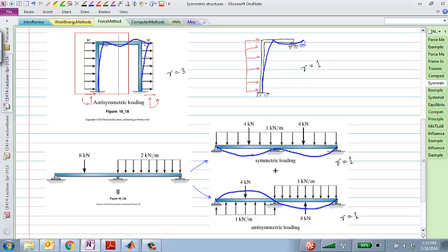And something like that. So, any idea what this vertical reaction would be here? What would be this vertical reaction? Should be 0. So, in fact, if you make use of this symmetry, your anti-symmetric structures sometimes turn out to be determinate. Okay. All right.